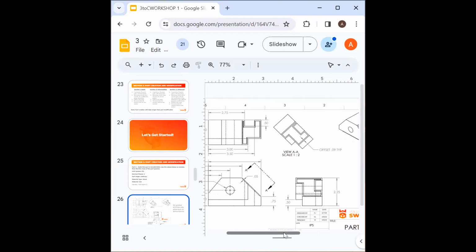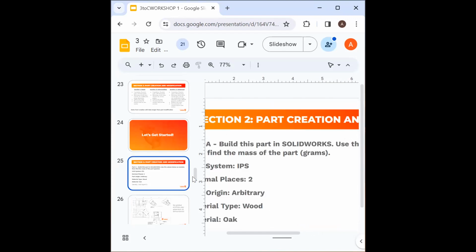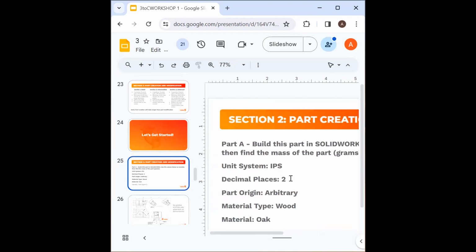Okay, so to start off, when you're taking the exam, the first thing we usually recommend is to set up your file itself. Like we mentioned, it's IPS, right? So when you go to the bottom corner here in SolidWorks, it'll show IPS. And you have other options like MMGS, CGS, or MKS. We're going to click IPS. Then you're going to edit your material. To edit your material, right click on material, or simply click on it if you only have a trackpad. Edit material. Let me know if I'm going too fast, by the way. If you can't find the material because it has folders on it, you may want to...